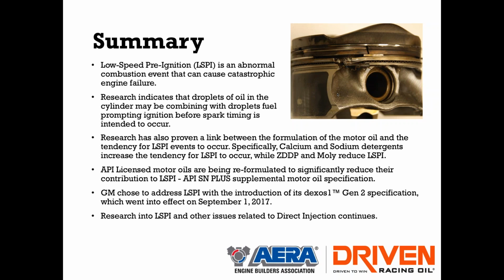LSPI is obviously an abnormal combustion event that can cause catastrophic damage. Research is showing that the oil and the fuel mixing together is the problem, and specifically it's the calcium and sodium detergent levels in the oil that basically are the catalyst to this being a problem.